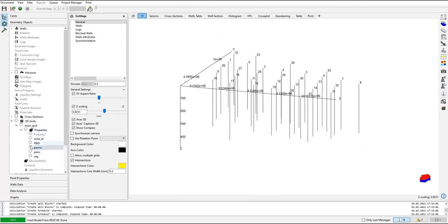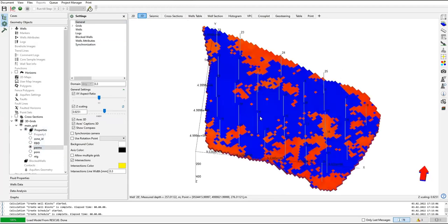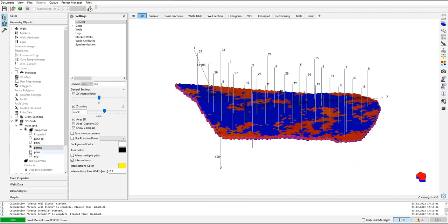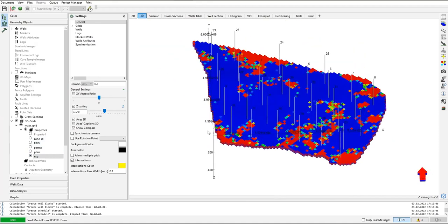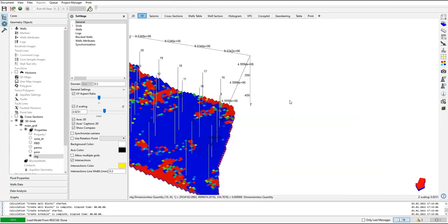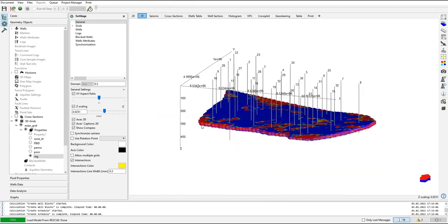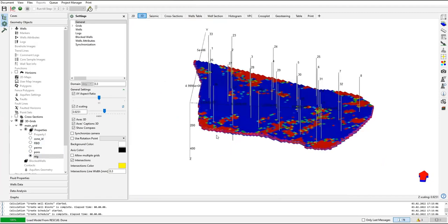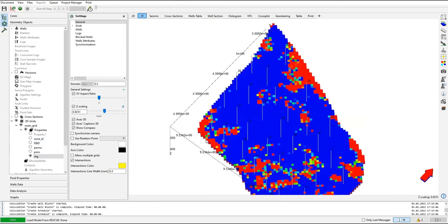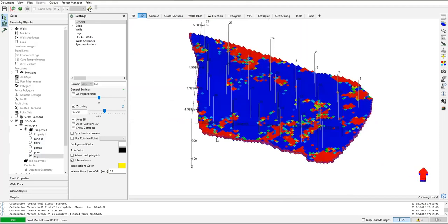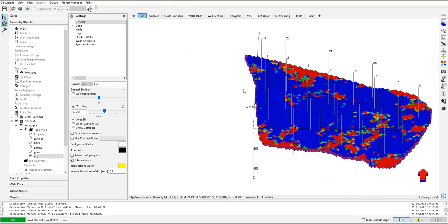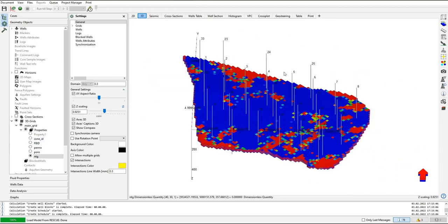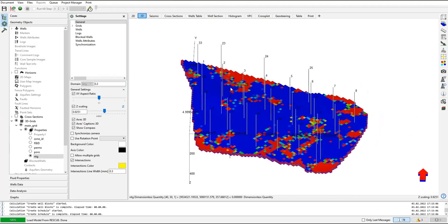Let's plot perm_X. It's like this: permeability in X direction, the porosity, the NTG. That's basic. And also, if you want to change the direction, like what I do here, you can just press the left key on your mouse, hold, and change it like this. If you want to move all of them, right click on your mouse, and you can move. I'm still holding the right key. If I want to zoom in and zoom out, just scroll.